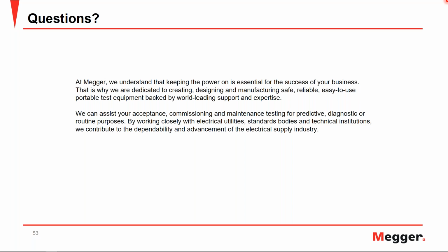Usually, I've seen utilities that do testing every 2 years. Other utilities do testing every 5 years. It also depends on what the testing practices are. Any data that you collect on insulation power factor will be beneficial for the future. You can trend values, you can collect data and see if there's any deterioration. So you don't have to do it every year,